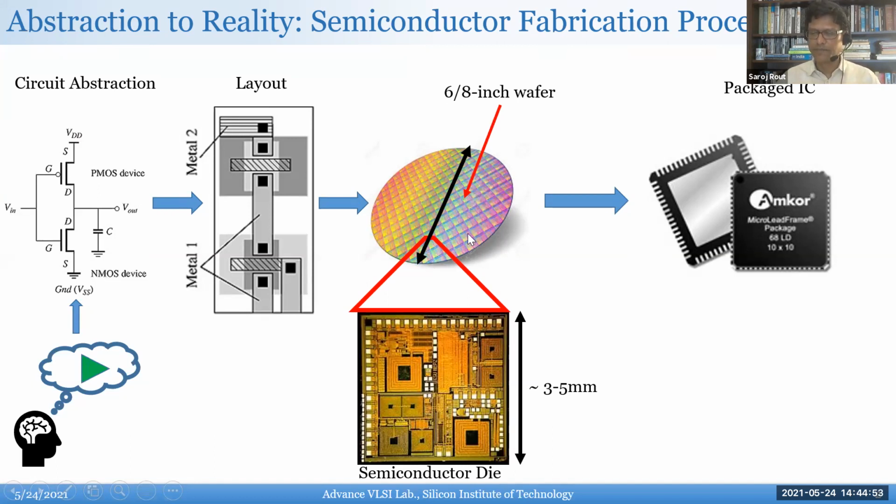As I was saying, the photolithographic exposure is actually done stepwise. They don't have a huge mask like this. They usually have what's called a reticle size, so they keep exposing by stepping a certain size of these chips. But once the processing starts, obviously it has to be done in one shot. It's not like a PCB where you're taking devices one each from the shelf and soldering them.